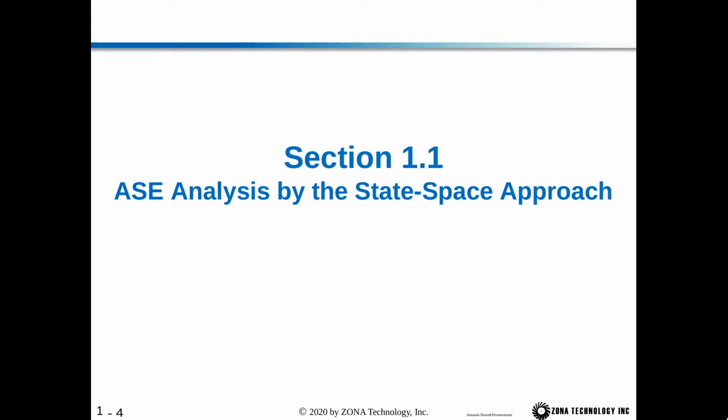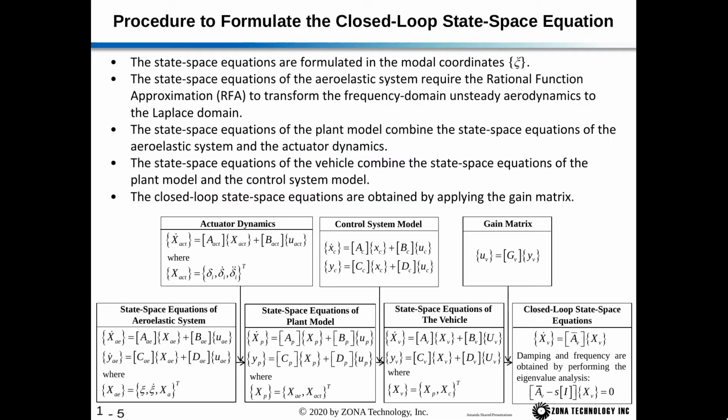So section 1.1, we'll start out talking about the ASE analysis by the state space approach. So first we'll talk about the procedure used in ZAERO to formulate the closed loop state space equation. The state space equations are formulated in the modal coordinates ξ. The state space equations of the aeroelastic system require the rational function approximation, which transforms the frequency domain unsteady aerodynamics into the Laplace domain. The state space equations of the plant model combine the state space equations of the aeroelastic system and the actuator dynamics.